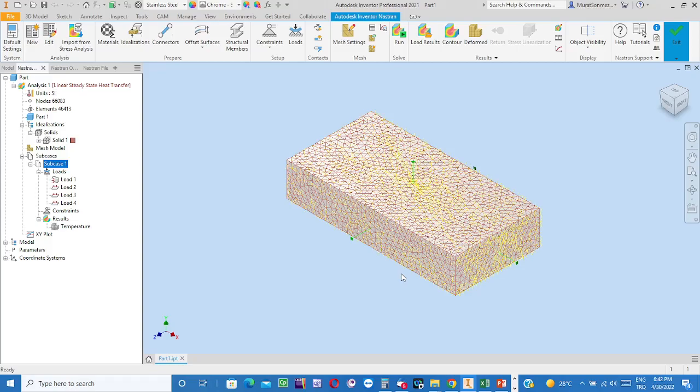Okay, at higher temperature, the strength of the material will be smaller. While the temperature is increasing, the strength of the material decreases. Okay, well, unfortunately in NASTRAN, we haven't got a push button to teach the software that it is a thermal stress analysis type problem.